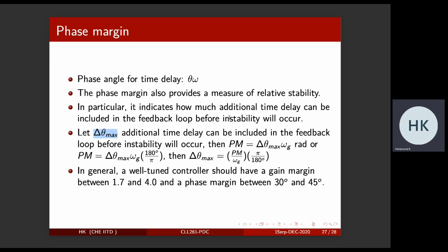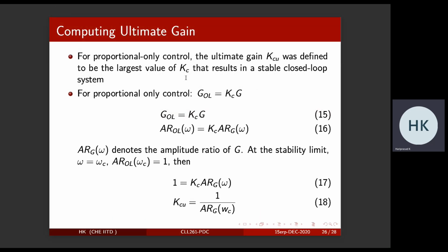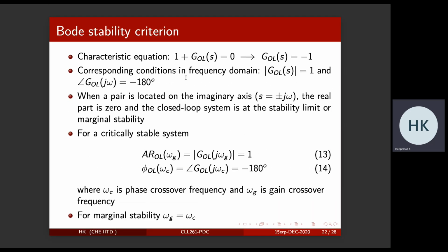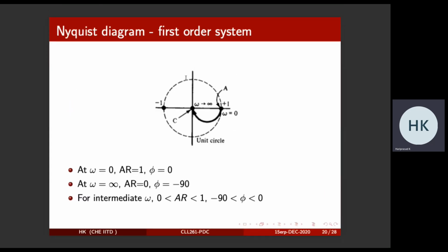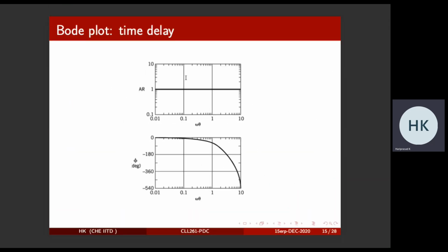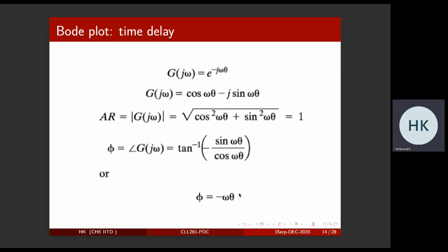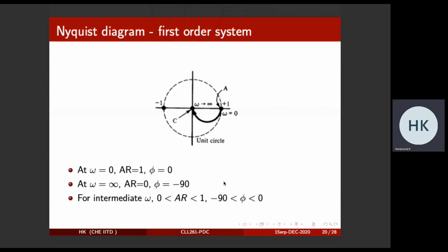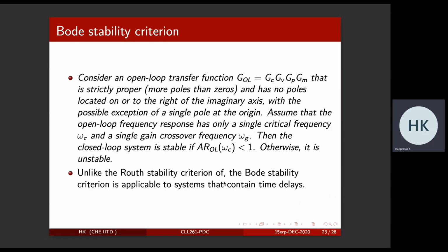The phase margin is theta(w); that is the phase angle for the time delay. This we have computed here. So we can accommodate that much extra time delay.